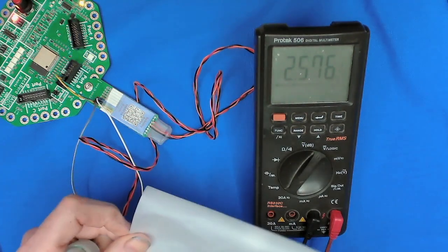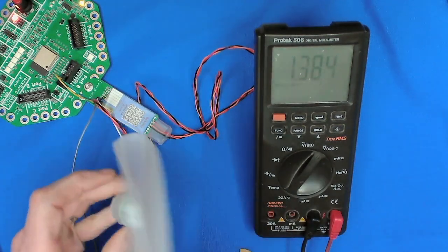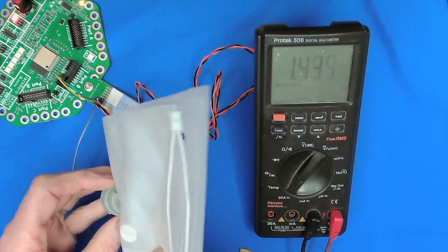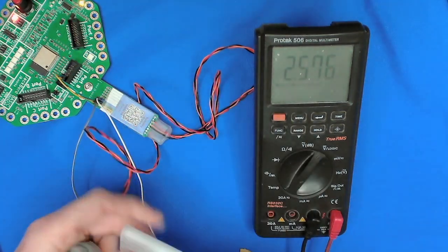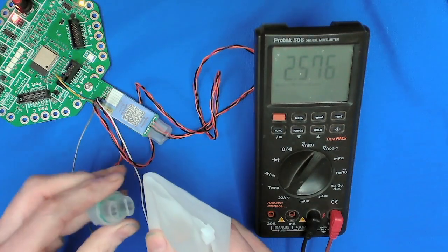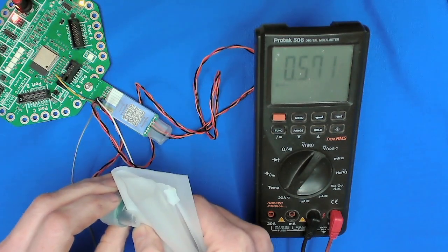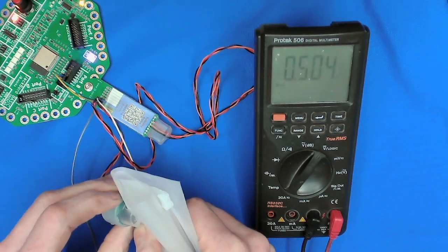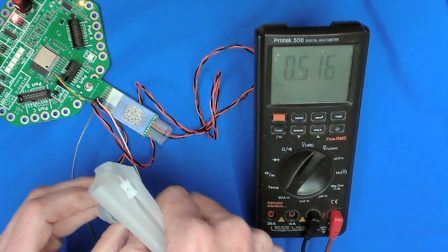So you can't see through the bag, but the turbidity is not that high. But then if I was to double it over like this, you can see the turbidity's gone a lot higher, so it's about 1.4. So as the infrared light finds it more and more difficult to penetrate, the turbidity gets higher. So if I put this in, this is 4 layers, goes down to about half a volt. So this is a measure of the turbidity. So you can see it's not 0, even though we can't see through this, the turbidity itself is not 0 yet.